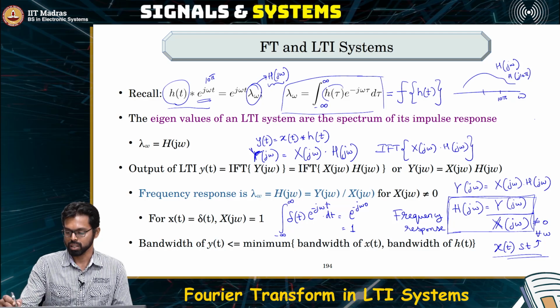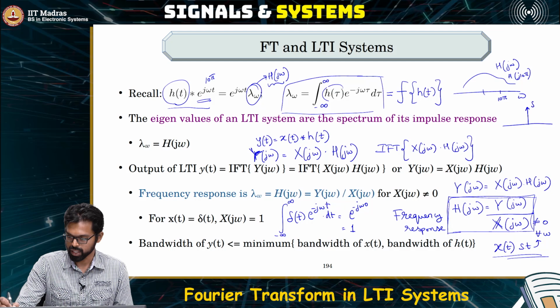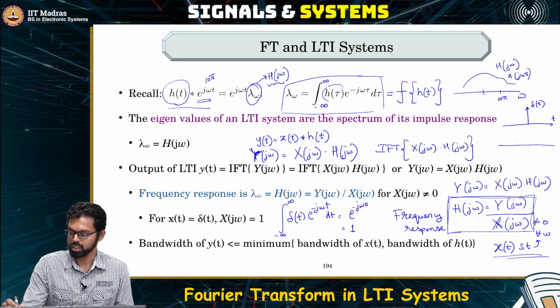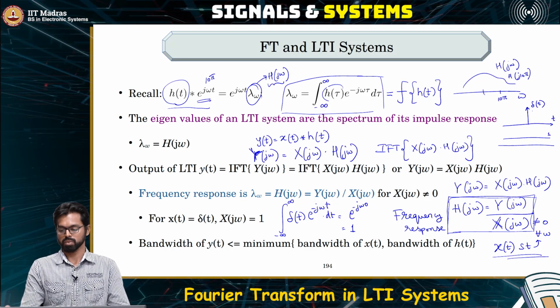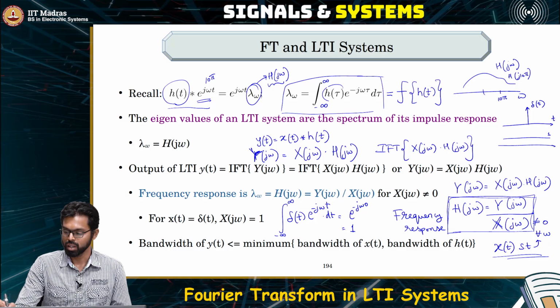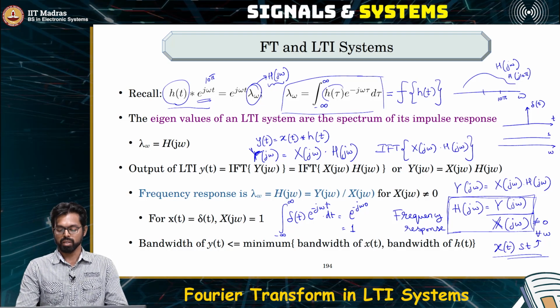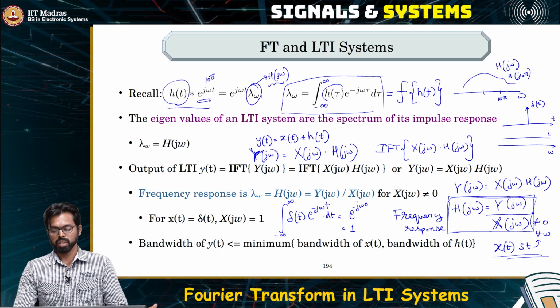This is quite interesting because the Dirac delta is a sharp line like this in the time domain, and the corresponding spectrum is a straight line which is equal to the area of the Dirac delta. The amplitude of the straight line in the spectrum is equal to the area of the Dirac delta, which means this also reinforces our uncertainty principle that we studied earlier.